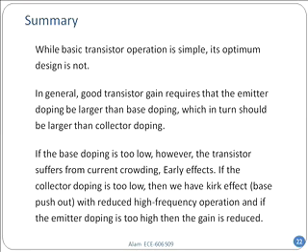If you reduce the base doping, what happens? Base series resistance, current crowding, and as a result, non-uniform turn-on. So that's a big problem. And I also have trouble with early voltage if I have a low base doping. My gain is not uniform with respect to the input. So then I go to the collector side, where I need a large depletion width and reduce the collector doping so the depletion mostly proceeds in the collector side.